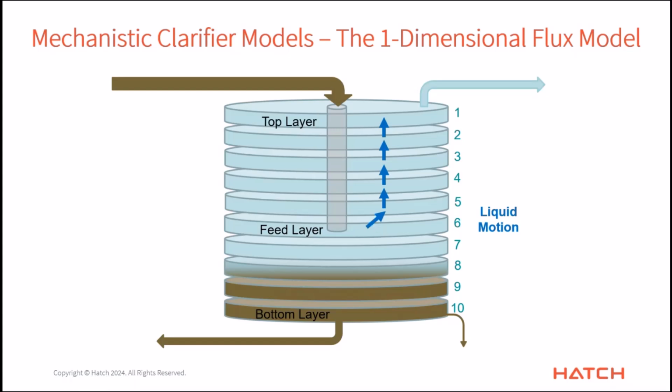And we have two aspects that we are keeping track of with our settler model. One of them is the liquid motion. So that is the flow of the actual wastewater, and in this case, at the high concentration of the mixed liquor. Some of that flow goes up and out as part of the effluent, and some of it goes down and is wasted or recycled. So based on the relative recycle ratio, we solve those flow balances first. And then we know that when there's 1 meter cubed of liquid that's being moved up here, it's going up in this direction, it is going to carry solids at the concentration of this layer into this layer. And that does allow us to be able to do a mass balance around all of the flow. And every place where that flow is moving through a layer, it is carrying some solids with it at a predictable level. So that's one part of the mass balance.